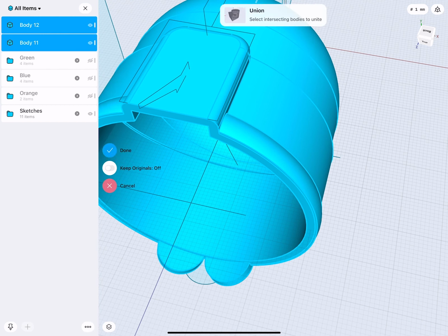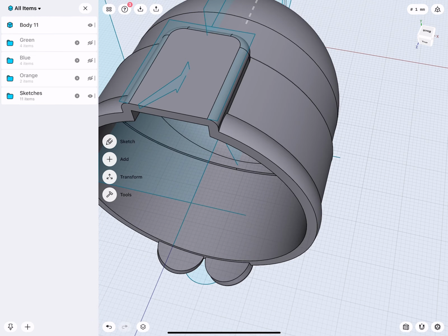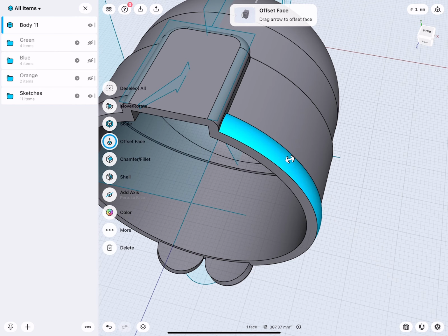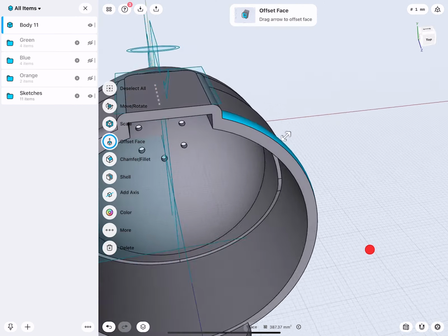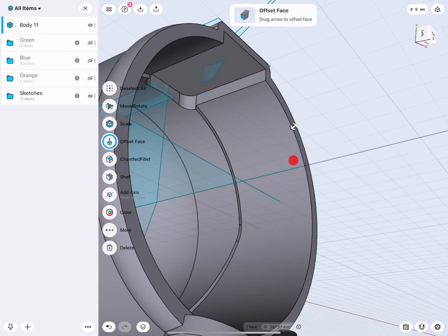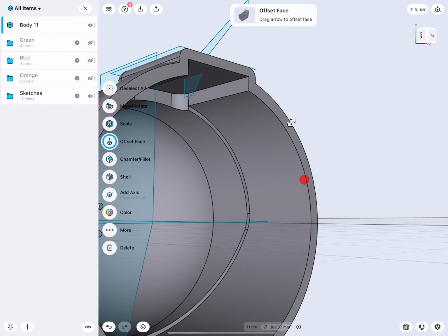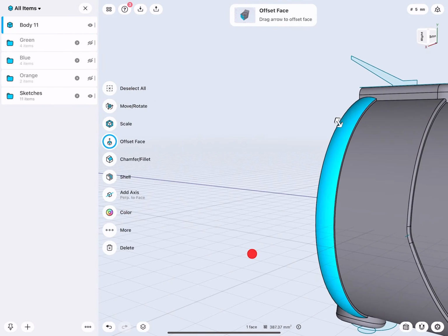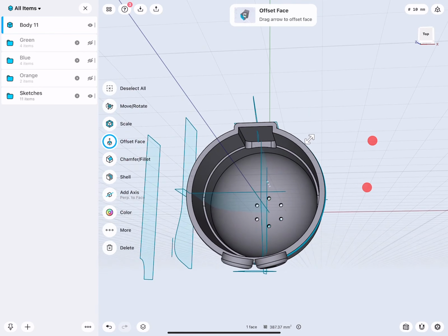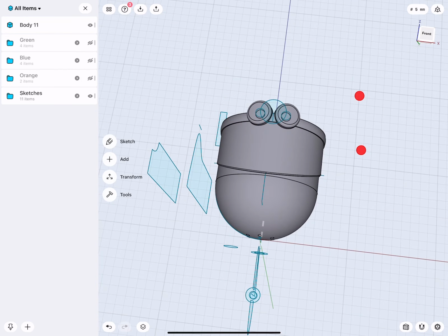The reason why I also join this element at the end and haven't joined it before we did a shell is simply, and I will show you this in another version, well, this face here is arced. And then we would also have here this convex. Wait, no, this is convex, this then would be concave. And here I just wanted to have a straight, flat face, which is the reason why I need to add this afterwards. Very good.